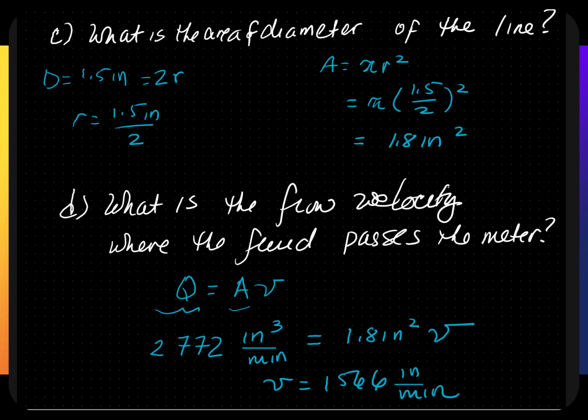Note all the gas laws. Boyle's law is PV equals PV. Charles' law is volume over temperature. Gay-Lussac's is pressure over temperature. Read the question carefully. If they're asking for absolute pressure for gas laws, you must convert the initial pressure into absolute or the total pressure. Temperature must always be converted to absolute scale, or degree Rankine is equal to degree Fahrenheit plus 460. You cannot use Fahrenheit because Fahrenheit has negative values, so you're going to have negative volumes.